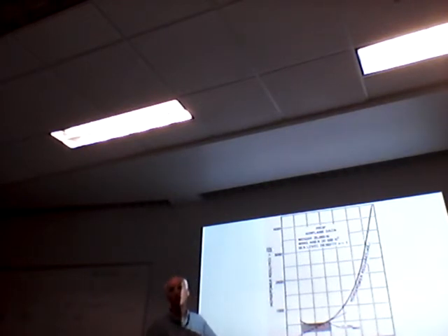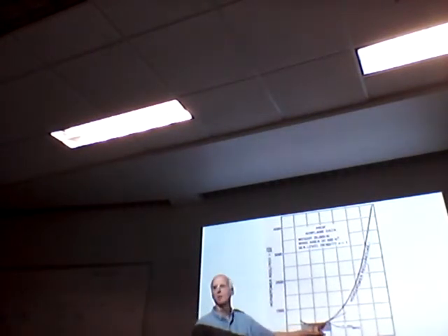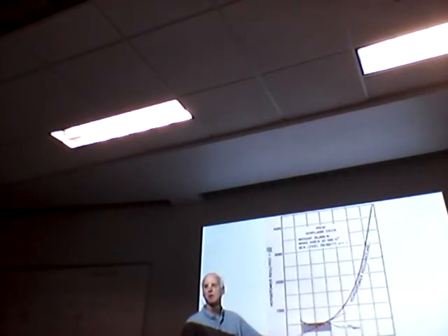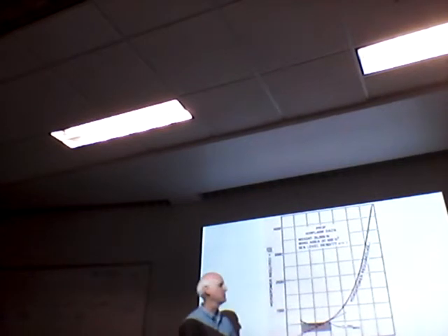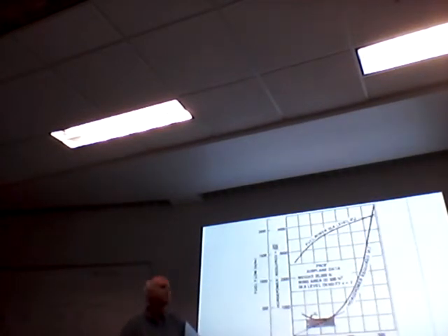I see what you're saying. Okay. Essentially, the tangent line is just like a 45-degree line that cuts. Not necessarily 45, it's wherever you start at the origin and wherever it touches the curve. So again, if I was in a headwind situation, I start at this 100 point, the tangent line is going to be out over here, and that's going to be my appropriate climb speed. A little more power if you do that. Yeah. Now, here is the same kind of thing.